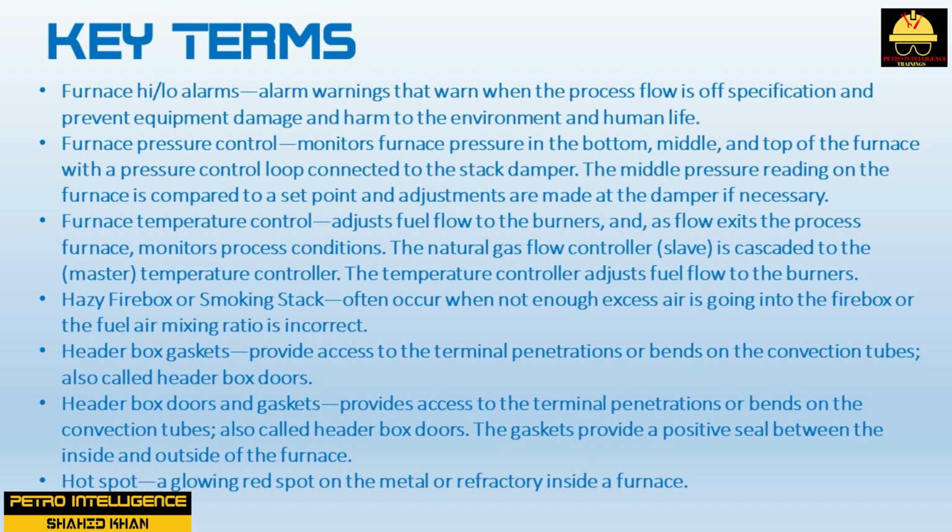Furnace temperature control adjusts fuel flow to the burners, and, as flow exits the process furnace, monitors process conditions. The natural gas flow controller, slave, is cascaded to the master temperature controller. The temperature controller adjusts fuel flow to the burners. Hazy firebox or smoking stack often occur when not enough excess air is going into the firebox or the fuel-air mixing ratio is incorrect.